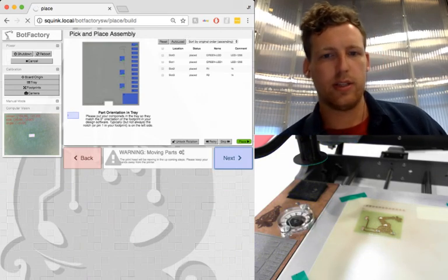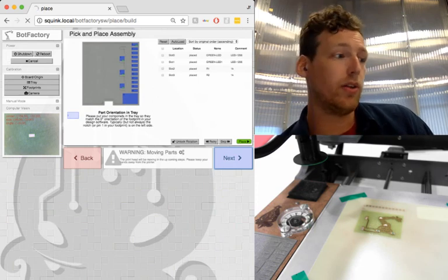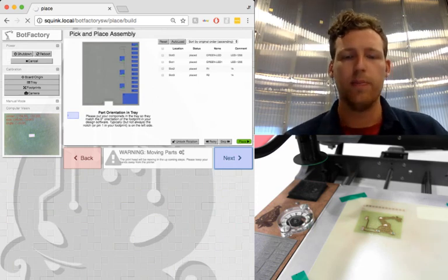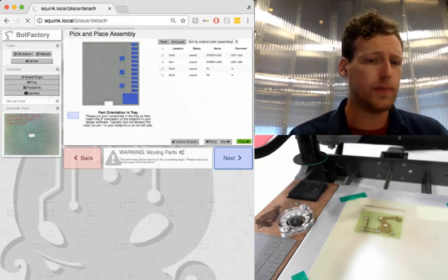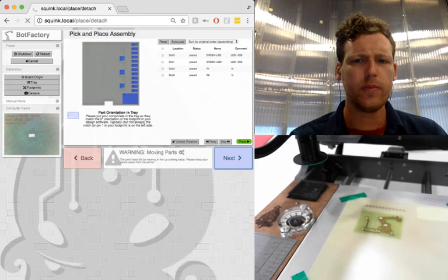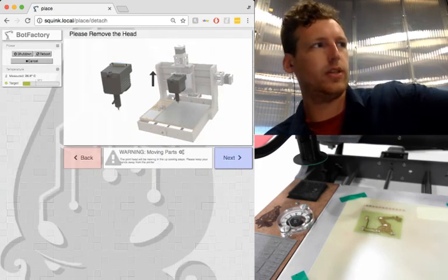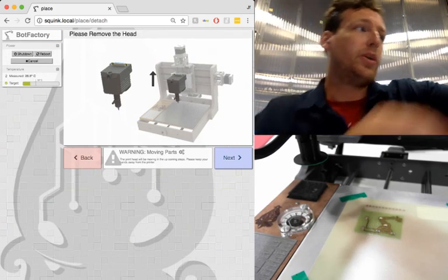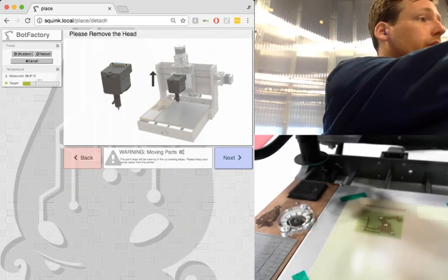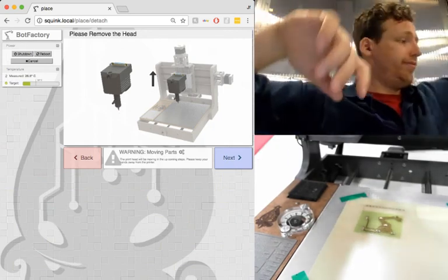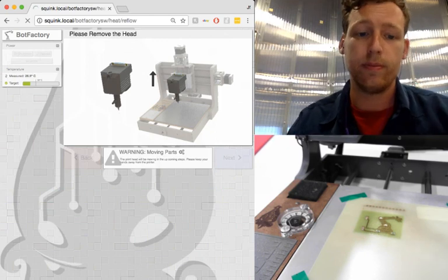Squink takes its time, and basically what's going to happen is I'm going to run it through a 20-minute heat cycle. You can run it at 10 minutes, it doesn't matter. You just have to cure it for around, I believe, anywhere from 70 to 100 degrees Celsius, and the glue will essentially cure. Because it's a two-part epoxy, it will actually cure by itself within 4 hours, but heating it accelerates the process.